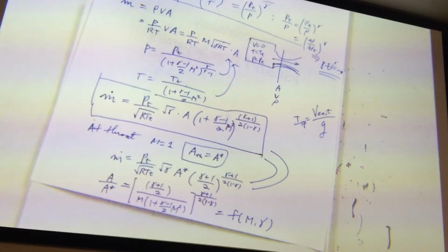Of course, when you have a small rocket, the real effect comes in, right? Because the friction force on the surface becomes more important. In a big rocket, you have this big exhaust, and your surface area is proportional to the radius, right? Your circumference is 2 pi r. That's where you have the friction, right? But your exhaust area is pi r squared. So when it becomes smaller, the frictional force becomes relatively important. However, in the idealization or as a first calculation, you can find out that it really does not matter how big your rocket or the nozzle is. It is A over A star.